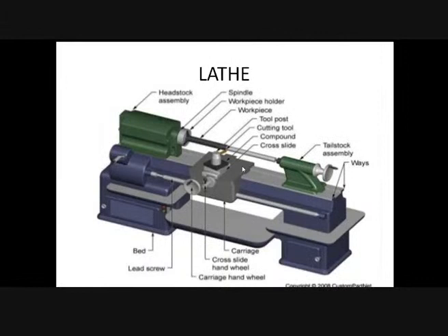Because the presence of cementite is in the form of granules, this will give you high damping in addition to high rigidity. So the material used in lathe bed is gray cast iron.